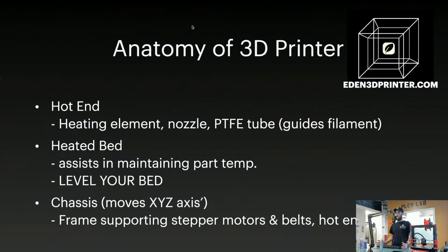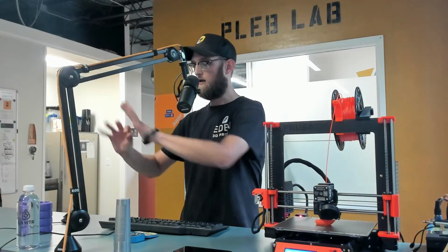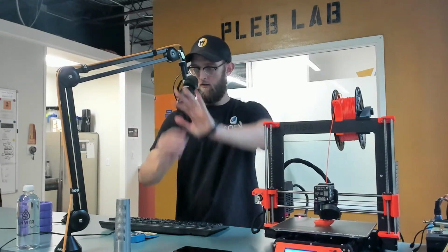So we're talking about the printer, and you're saying, okay, great, what does extrusion mean? I don't know what you're talking about. What is filament? What is a tool head? Let's just very quickly go through the anatomy of a 3D printer. You have your actual operating tool head, and that contains your extruder, if it's a direct drive, but we don't need to get into details, and it will include your hot end, which is what actually melts the plastic. So it's very simple. It takes plastic on a roll, like a weed whacker string, a trimmer string, and it puts it into a small nozzle, a little orifice. I have an example here, a very small orifice, and it extrudes that layer upon layer upon layer to build your model.